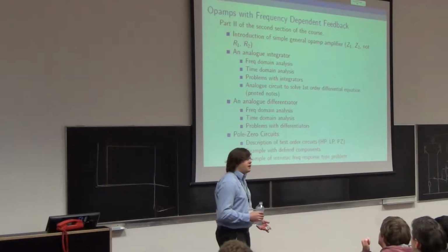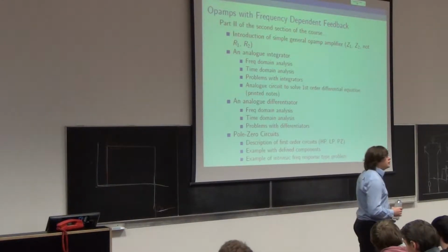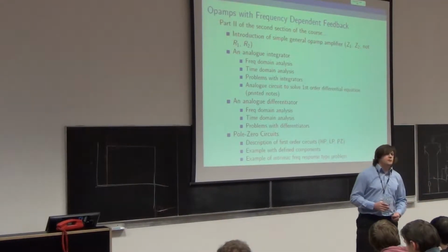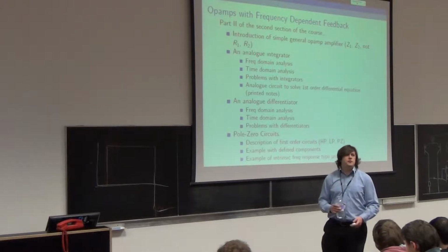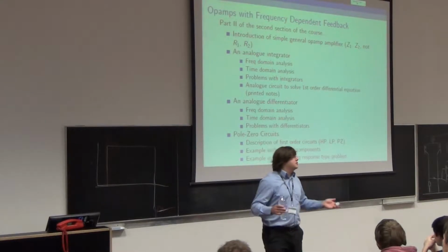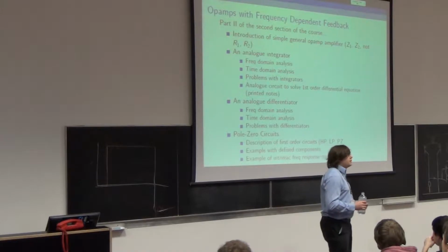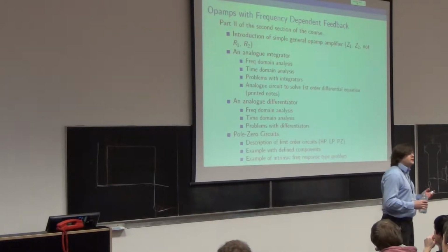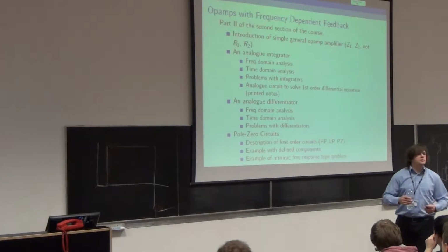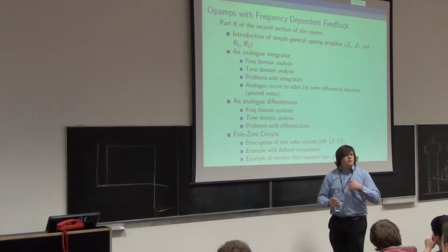For example, let's imagine you make a common base amplifier and you're going to use it as a transimpedance amplifier, and you will connect to it a photodiode to receive a signal from a laser coming down a fibre optic cable in some communication system. Entirely plausible. You will have to go to some length to bias your photodiode because you've got to put a big depletion region in there to extract the carriers and turn the photons into electrons and get the electrons out. So you need to put a voltage across it.